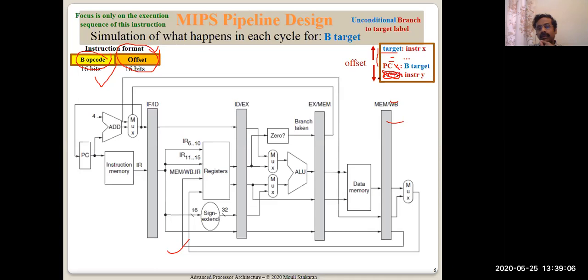It has to give with respect to PC plus 4, because PC plus 4 only is used by the pipeline to compute the new address. So the tool is aware of it. So it puts the offset value into the instruction, sorry. Along with the instruction, it comes. Now, you can write the equation now. Target in terms of offset. I am sure you will be able to write.